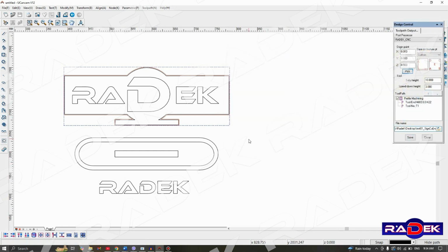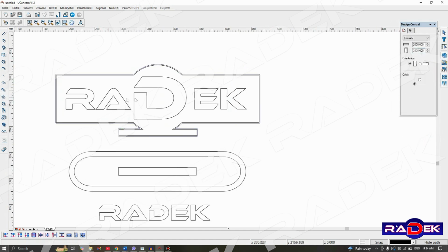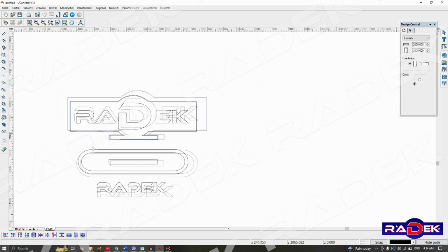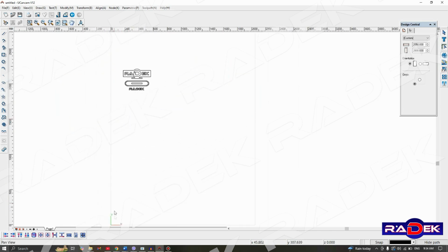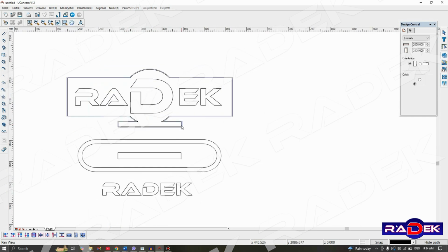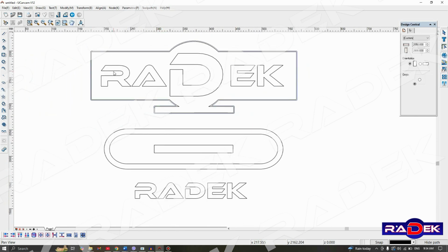With this, the software has successfully generated our toolpaths for cutting off the sign from the material. When we load this file into the machine, we need to make sure that the correct knife is equipped. In our case, it's the 3mm diameter end mill. And we need to make sure that the origin position is at the bottom left corner of the workpiece, identical to the origin position we set up in the software. So now we can move on with the remaining vectors and toolpath operations.